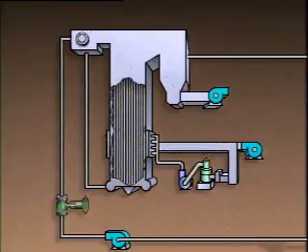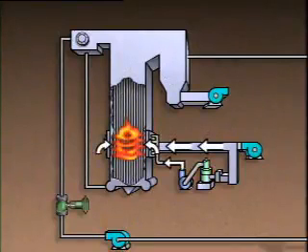After the boiler has been purged, you must perform the third step, returning the plant to normal. In this example, that involves relighting the burners and increasing boiler steam pressure to normal. If for some reason the burners can't be relit, the unit must be shut down. Keep in mind that you must know your plant's emergency procedures in advance. If you wait until an emergency occurs to study them, it's too late.